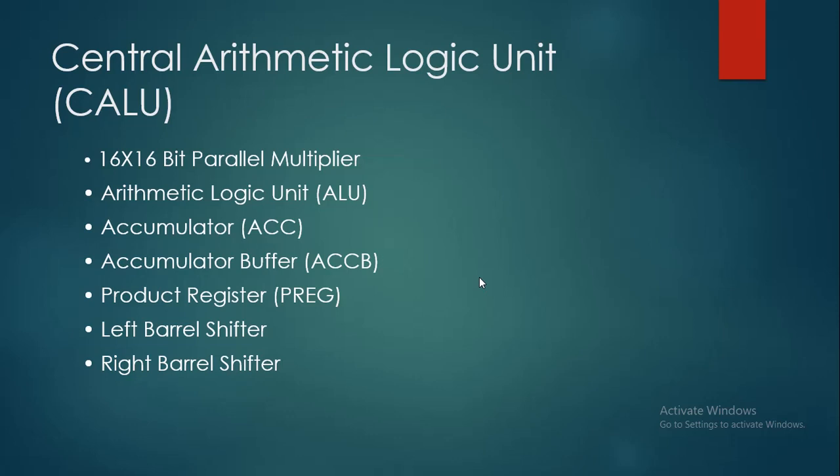The parallel logic unit is the second logic unit. It executes logical operations on data without affecting the contents of the accumulator. It can directly set, clear, test, or toggle multiple bits in a status control register or on any data memory location.